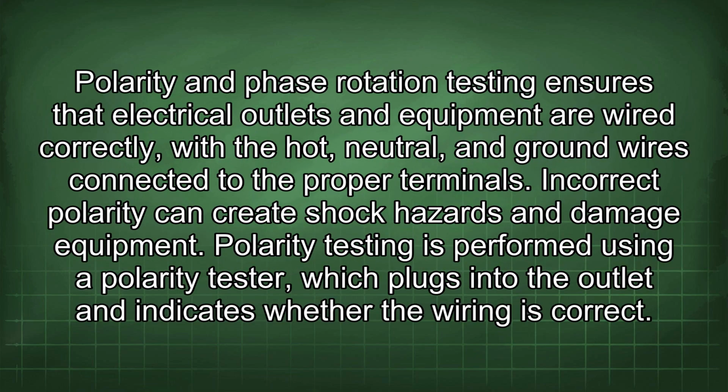system. Polarity and phase rotation testing ensures that electrical outlets and equipment are wired correctly with the hot, neutral, and ground wires connected to the proper terminals. Incorrect polarity can create shock hazards and damage equipment. Polarity testing is performed using a polarity tester, which plugs into the outlet and indicates whether the wiring is correct.